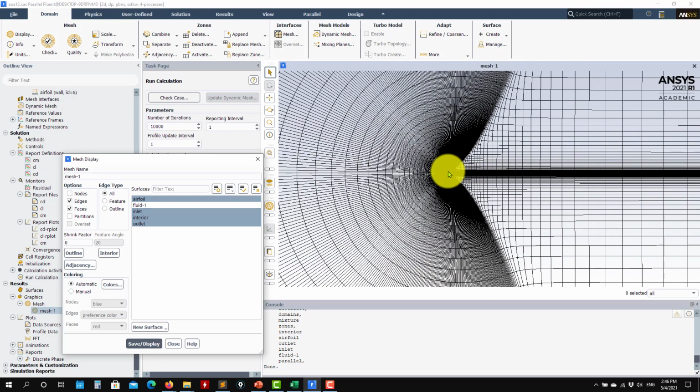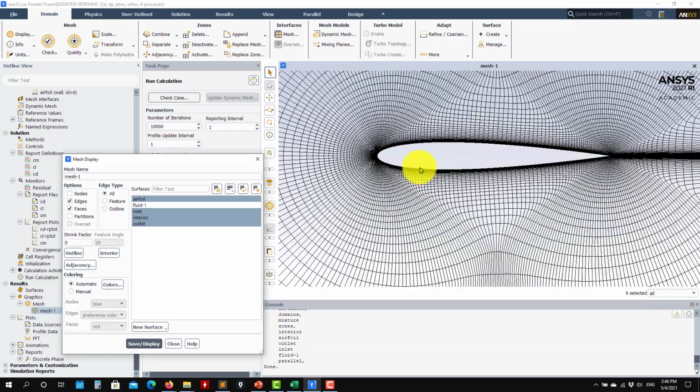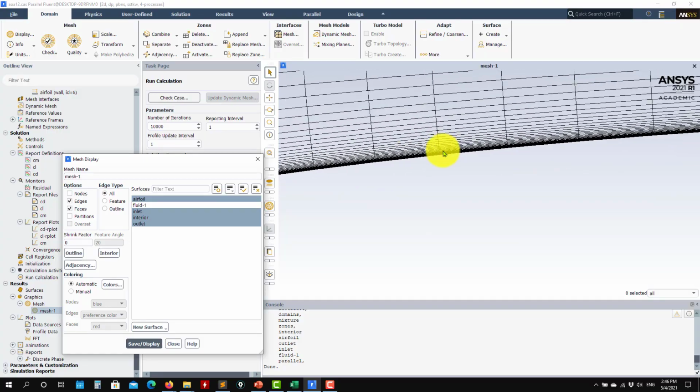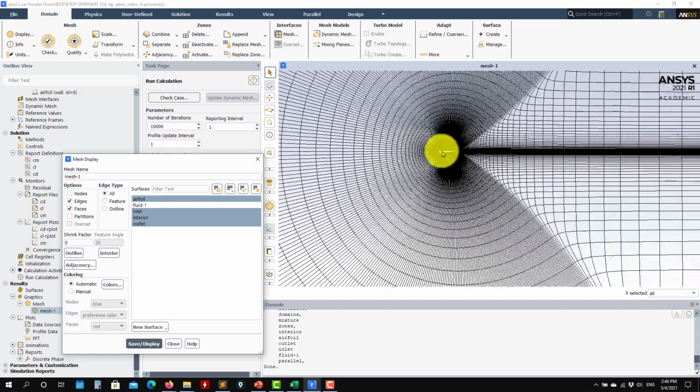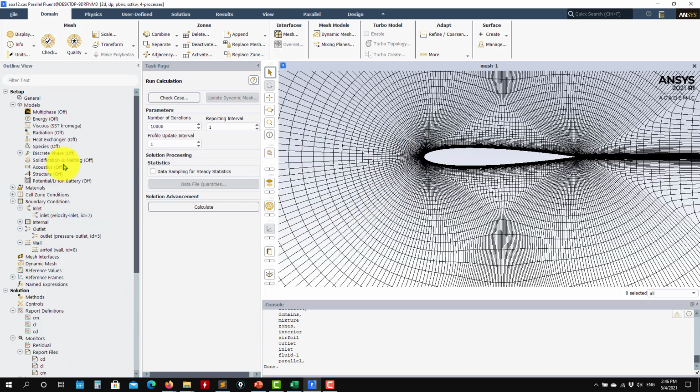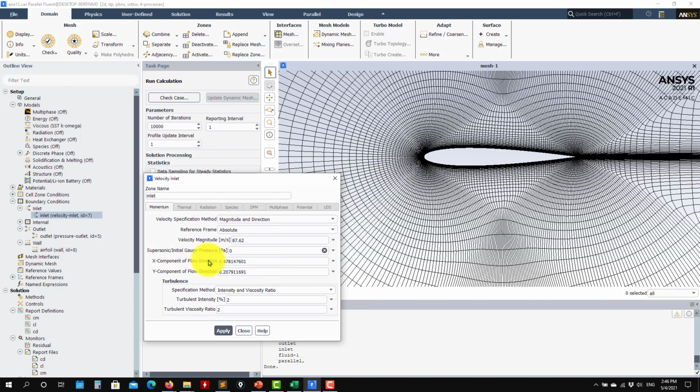This was using a structured mesh. And see that this is a very nice mesh, very refined. This is wall resolving. In this case, the physical angle of attack is always 0, but what changes is the incoming velocity. So it's 12 degrees. As you go to the case setup, nothing changed. Everything is exactly the same, but at the inlet you define your direction vector.